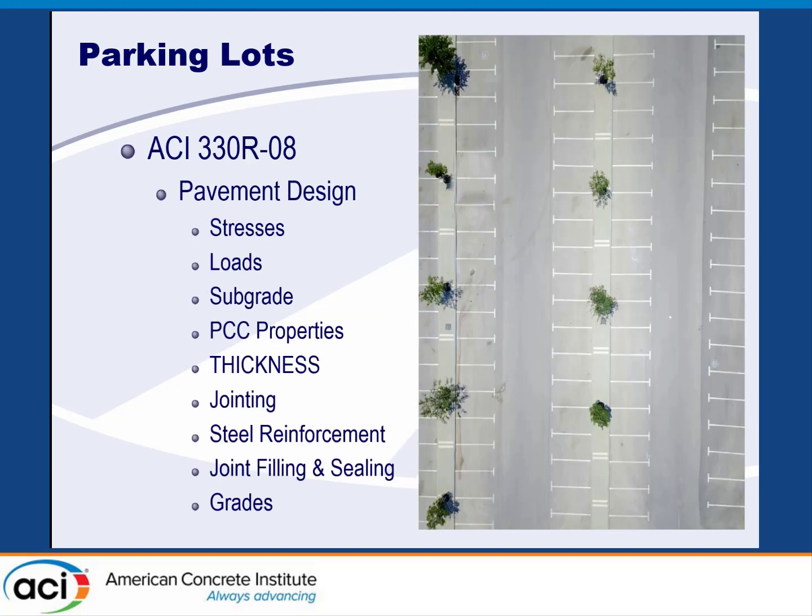If we look at that 330R08 guide, the document looks at a lot of the same things as the streets and local roads one, but it accommodates a few other things. First off, it looks at stresses in more detail for the concrete parking lot type of facility. It also looks at loads and subgrades just like our 325 document does, and then it gets into the thickness design. It goes through jointing a little bit, and it also goes through steel reinforcement, because that's sometimes more prevalent in parking lots, whether or not it's actually warranted or needed. But it does discuss that, whereas in 325 we're talking more about doweling our joints.